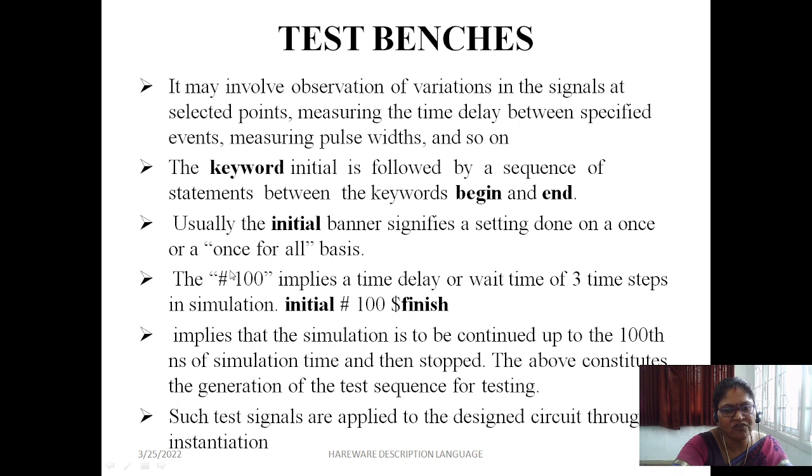So here we mention #100. This is for a time delay, or a waiting time for the simulation. So initial means it should be executed only once, and #100 means a delay of 100 nanoseconds, and $finish means your program will end. So we apply the test signals to our design circuit.